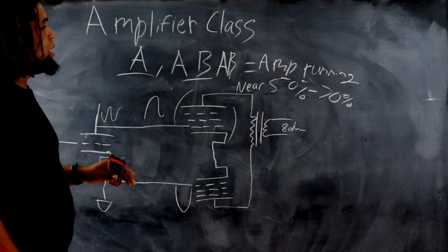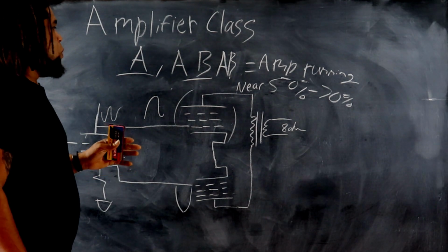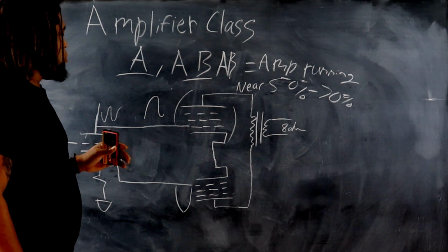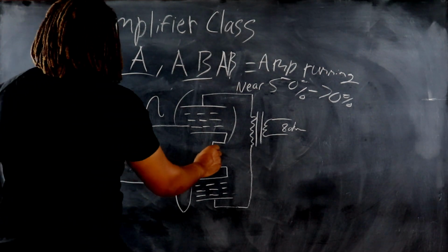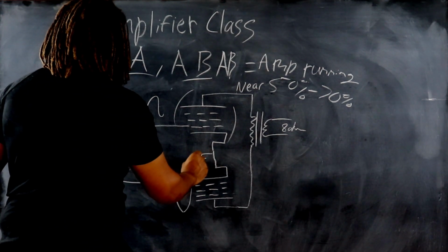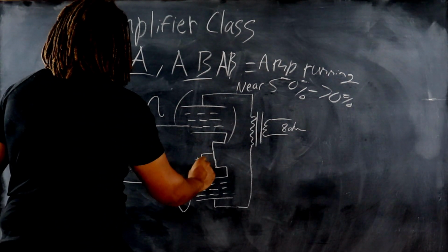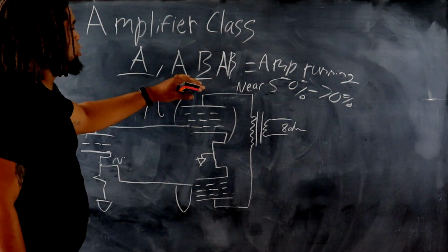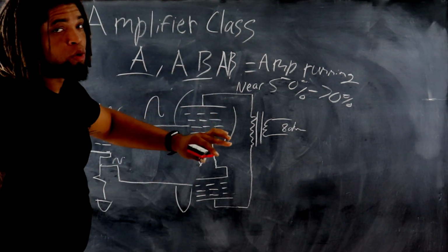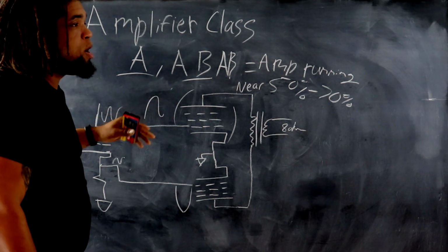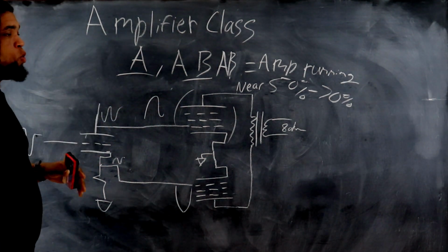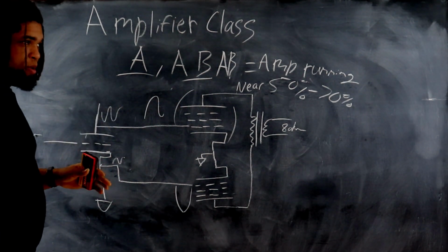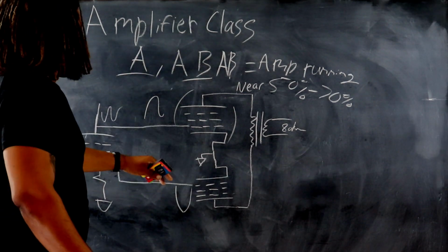And typically, manufacturers want to be more specific about how the bias is going to be, what the duty cycle is going to be, and what class they want to run it, because there's also a Class AB1 and AB2. What we're talking about here is basically AB1, but there's a Class AB2 as well. Now that is represented by how much bias voltage you would have here.